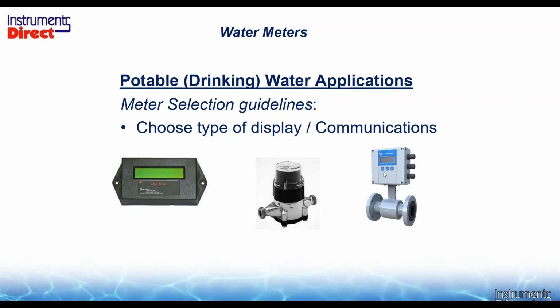or have a more diligent type of meter, where I have a programmable digital display that has more information. So on the process side, I may not just want to see total flow. I might like to see flow rate. So I want to see it in gallons or liters. I want to know the total flow. I may want to have it programmed for high and low alarms for my process application.